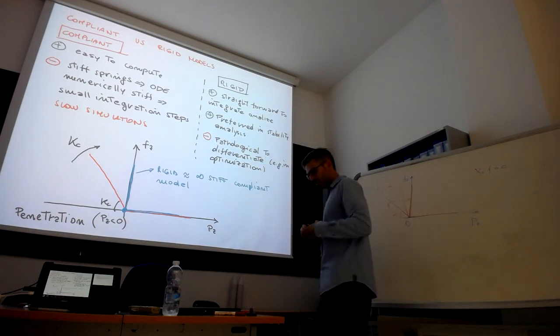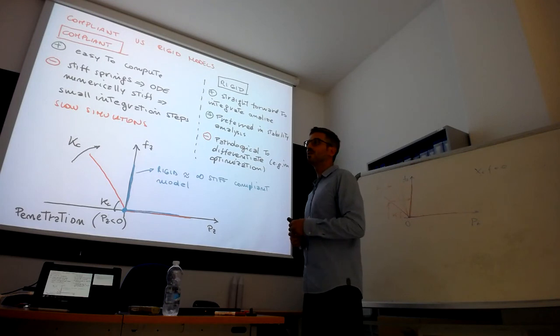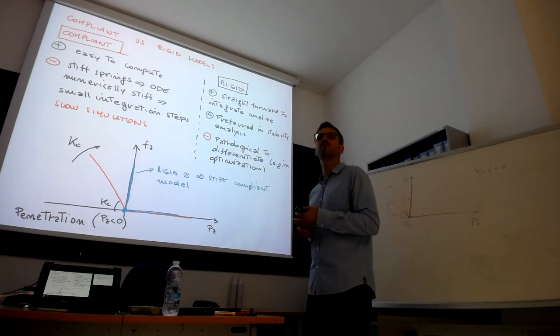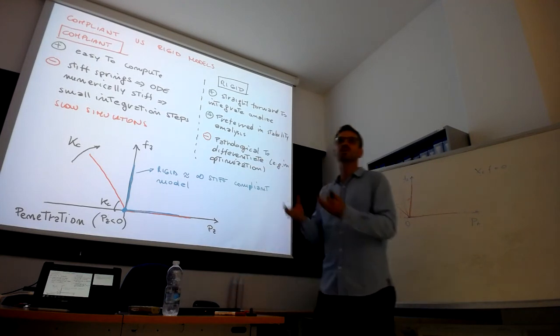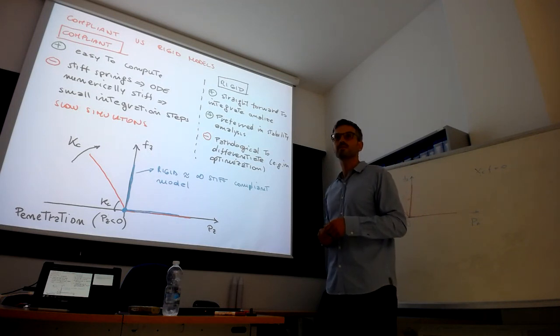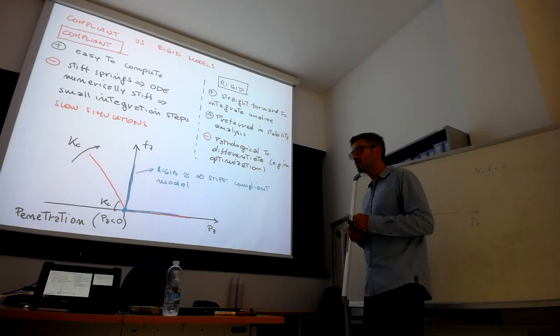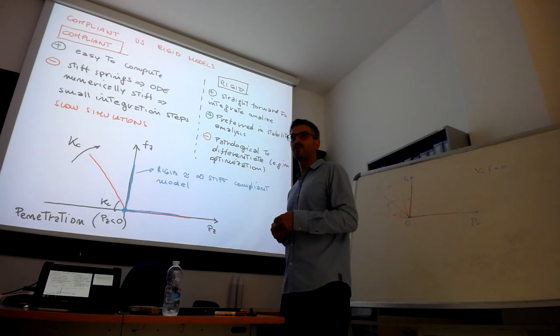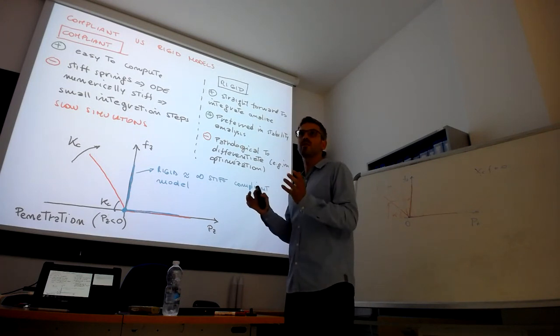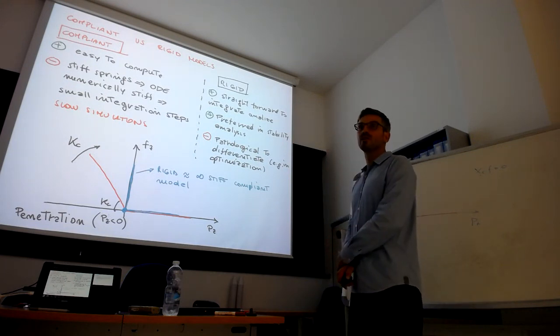Why do you use the rigid model for stability analysis? For example, because from the equation you can drop the contact forces. It's easier to do a stability analysis on the acceleration zone. I don't need to differentiate there. Think about when you want to do a Lyapunov stability analysis, and you don't want to have the contact forces inside. You just want the dynamic equation, and in that case, it's easier with the constraint dynamics.